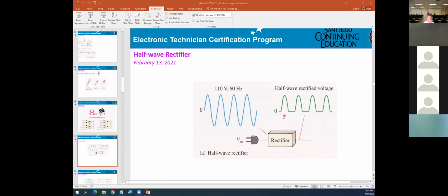However, on this one, when you get the current, it flows from the left to the right. This is no current, not a big deal. However, when you get the current, it is still flowing left to the right. That means one direction. That means DC. Okay. However, this is special, they call it pulsating DC. This is coming out from the rectifier.